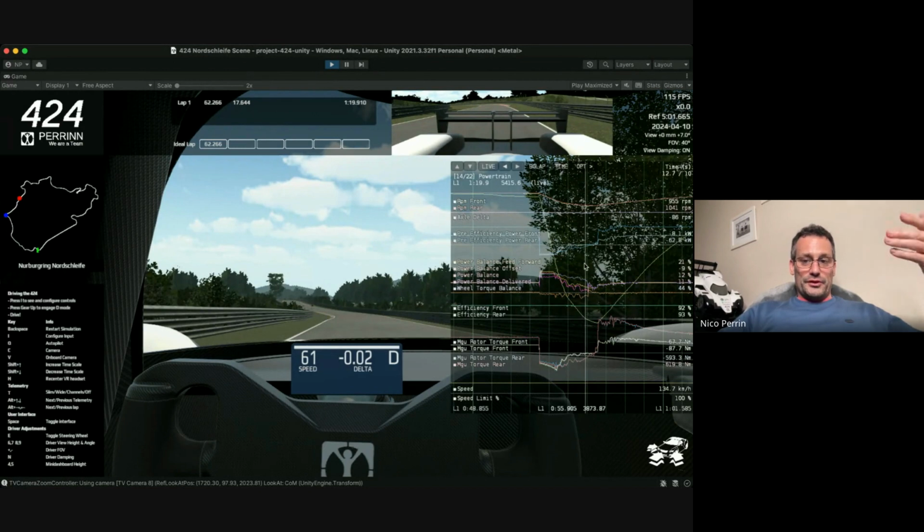The feed forward, which is what we calculate, is 15%, which means, mid corner, you still have some torque. You're off throttle, but we have what we call the overrun, which is like engine braking. It's a negative torque that slows the car a little bit like a handbrake. Why a handbrake effect? Because I just said the balance is 15%.